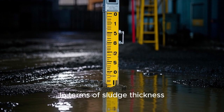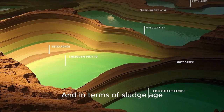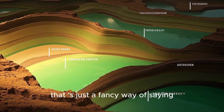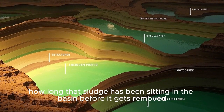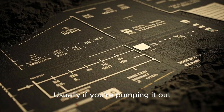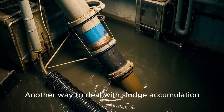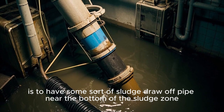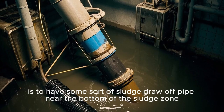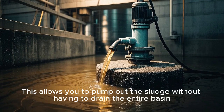In terms of sludge thickness, usually anything less than 1 meter is okay. And in terms of sludge age, that's just a fancy way of saying how long that sludge has been sitting in the basin before it gets removed. Usually, if you're pumping it out, you want to have a sludge age of less than 2 months. Another way to deal with sludge accumulation is to have some sort of sludge draw off pipe near the bottom of the sludge zone. This allows you to pump out the sludge without having to drain the entire basin.